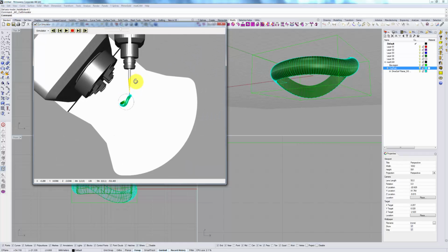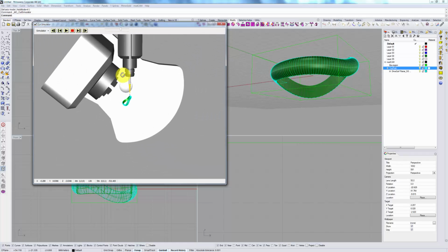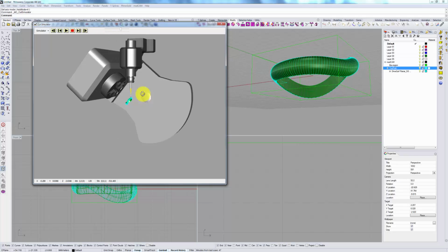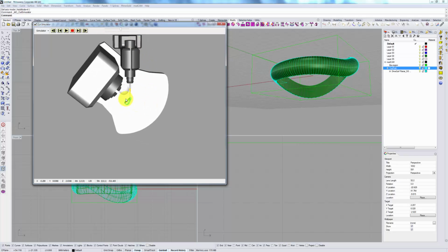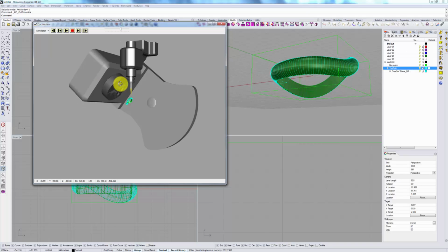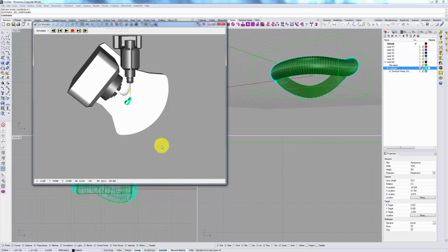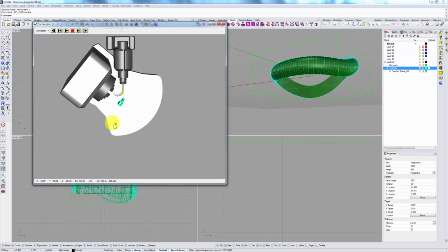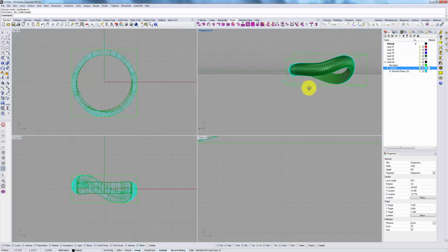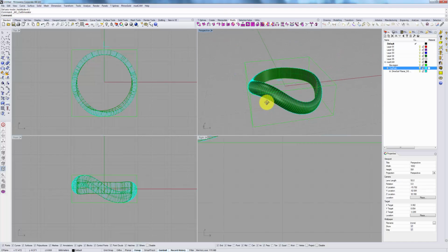So here you see why it's important to have our ring positioned far enough away from the chuck so that you don't get collisions. And likewise, you see why it's important to have a reasonable angle limit, in this case 130, defined, because any further and then this A-axis will start colliding with the spindle. So that's your 5-axis simultaneous.